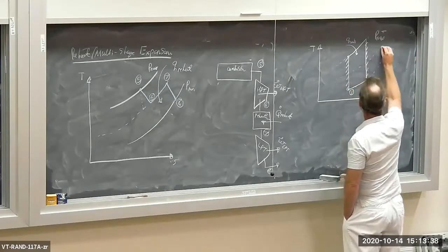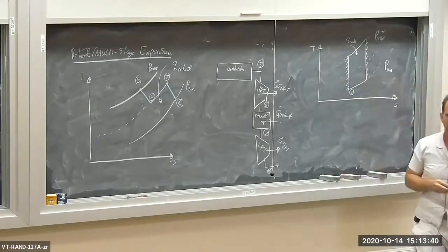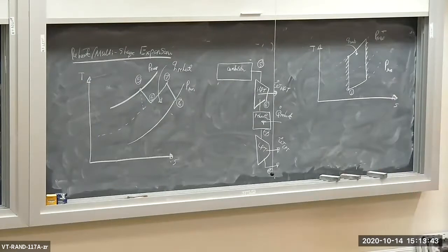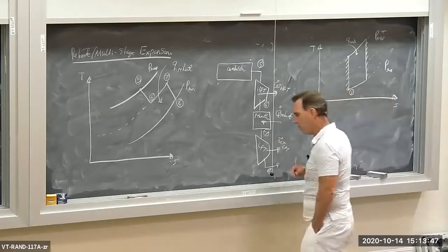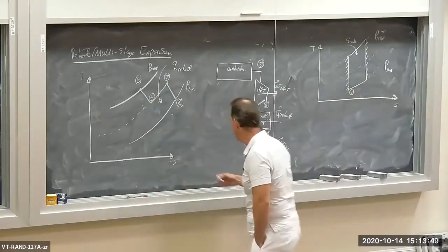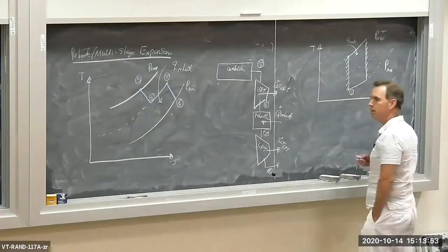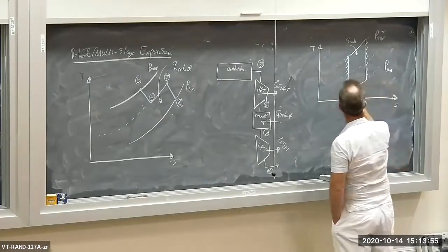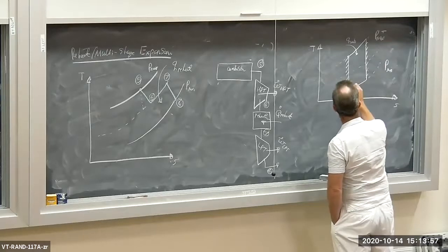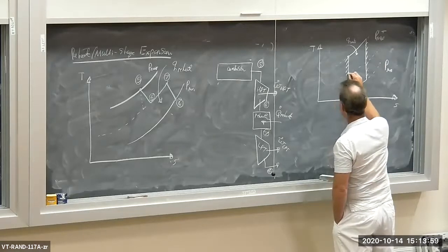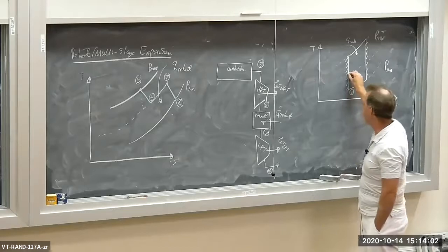So we put an intermediate pressure isobar in this TS diagram. Let's put an intermediate isobar. And now I'm going to overlay here. I got some blue chalk. I'm going to implement intercooling and reheating, and we're going to see what the cycle looks like. So I'm going to compress it up to the intermediate pressure in the low pressure compressor.